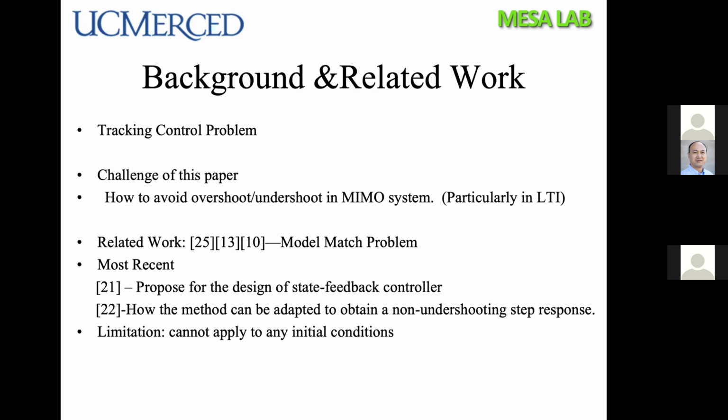Very recently, it has been shown in reference 22 how the method can be adapted to obtain a non-undershooting step response. The key idea behind the approach in these two papers is to design a feedback matrix that achieves the desired closed loop eigenstructures.